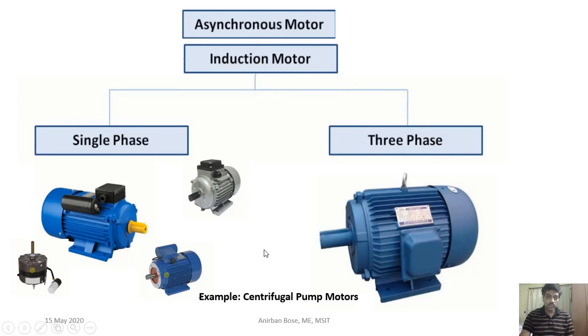Now these are used in centrifugal pump motors, both single phase and three phase. For smaller capacity pumps, like our household pump to take water to the overhead tank, we generally use single phase. But large industrial pumps may be operated by three phase induction motors.